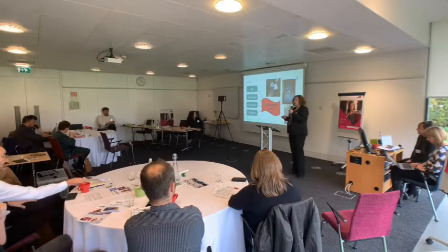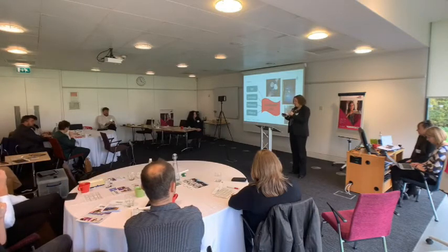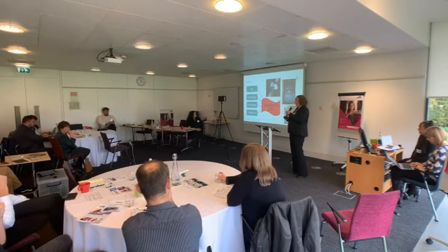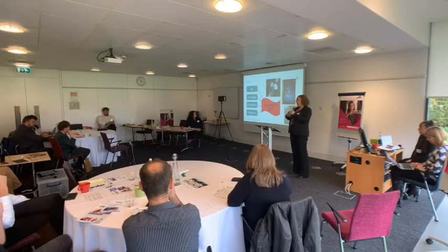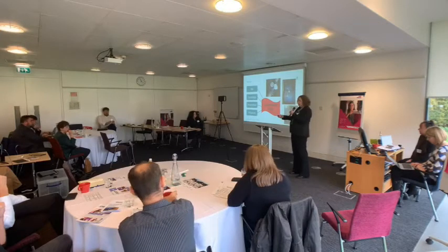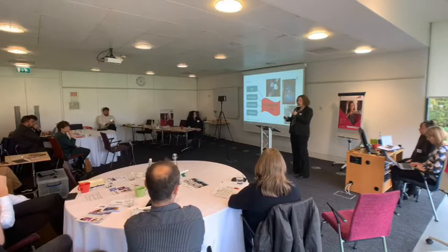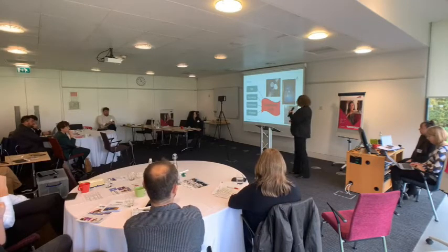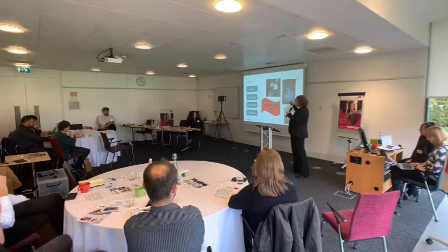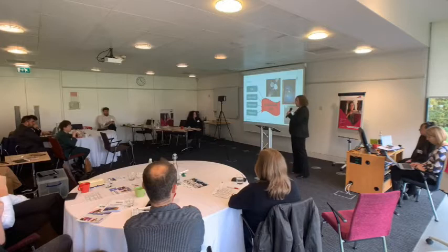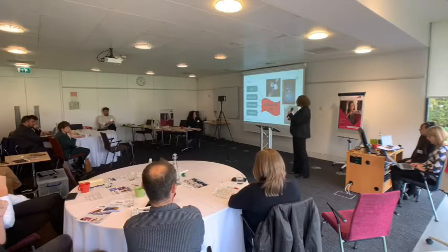And then we can use the sample of all those meters that have been tested to actually estimate a confidence band around that error estimate. So you can end up working out how to adjust your flows to get the most accurate idea of the real amount of water passing through the meter, and also understand how sure you are about that number. The pictures on the slide, I should just say, are of some big meters and also of a large meter test rig, a flow loop that can be used to test them.